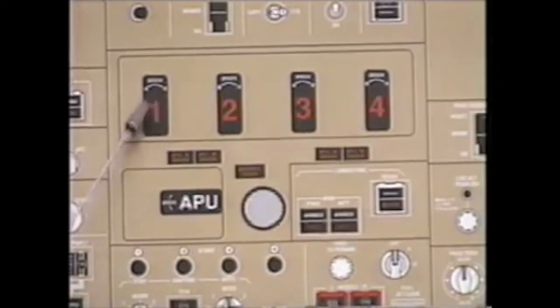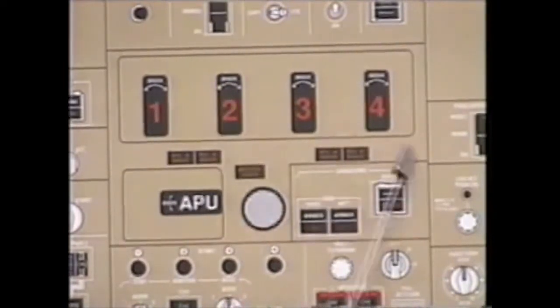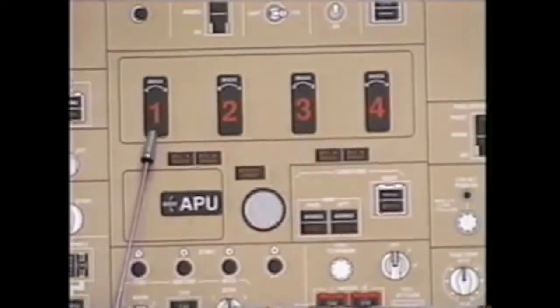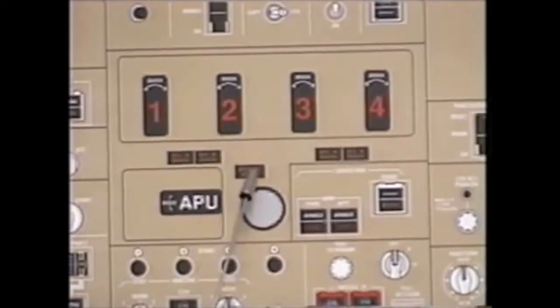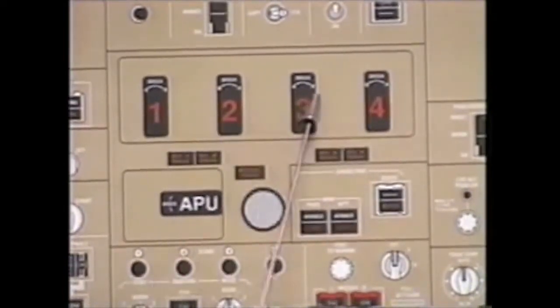Engines 1 and 2 on the left wing share 2 bottles, bottle A and bottle B. If you discharge bottle A into one of these engines, bottle B can also go into that same engine, or it could be discharged into the other engine. There is no way to get these 2 bottles on this wing over to this wing. Likewise, there's no way to get the APU fire bottle to either wing.